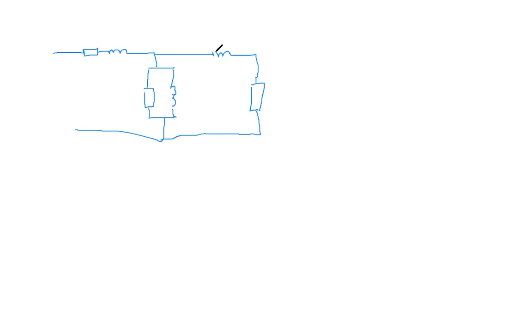Okay, right. So this is an equivalent circuit. All right, so this is IR. I want to work on this only so far. And this is jXS naught. And this is what? RR over S. And this we already know, it's XM. I want to concern myself with these guys here.